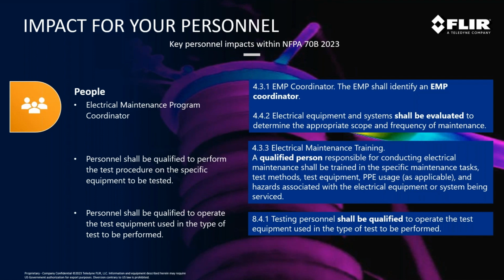Two real important ones to call out here too. So personnel should be qualified to perform the test procedure on the specific equipment to be tested. So this is not just thermally trained operators of cameras. This falls into any specific maintenance tasks, testing methods, equipment, PPE, as well as hazards and precautions around electrical equipment that's being serviced. This is really important to note.